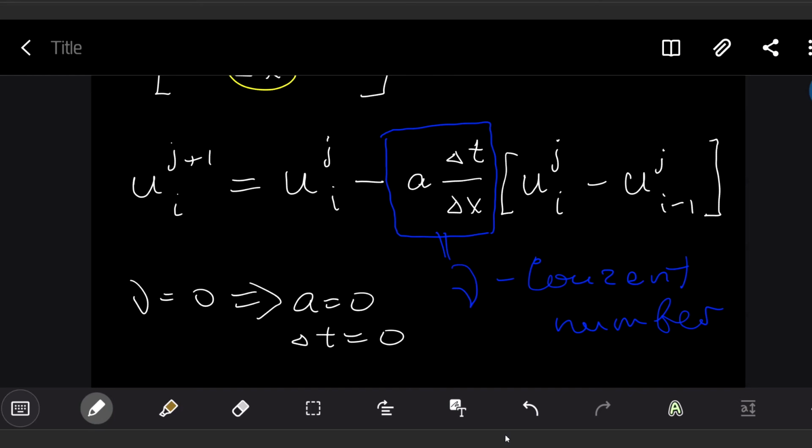So a Courant number equal to 0 or negative has absolutely no meaning to us because we are not moving forward in time to integrate our equation from its initial time step. A negative time step is not physical at all. So it's not possible to simulate back in time because time cannot be negative, and in this case the system is not stable. To know what is a stable and unstable system there is a strict mathematical definition. Go and read Anderson, Fletcher, Tannehill, which I uploaded to the system.